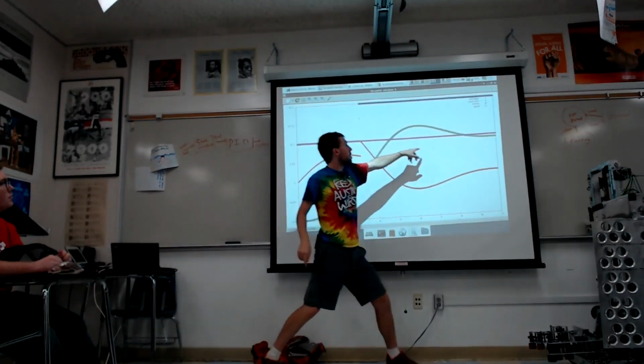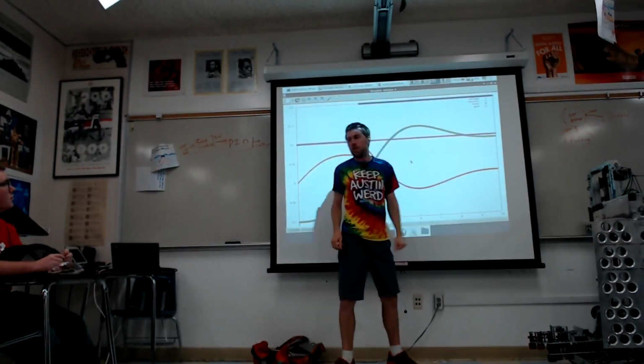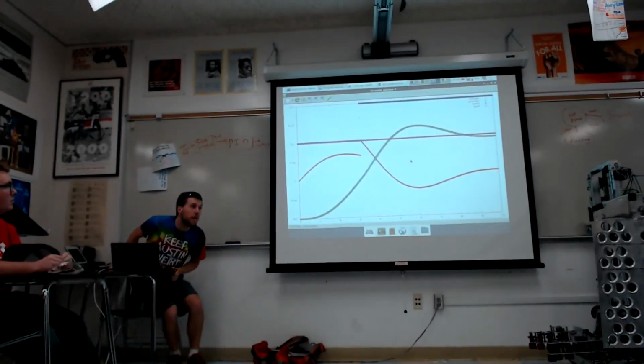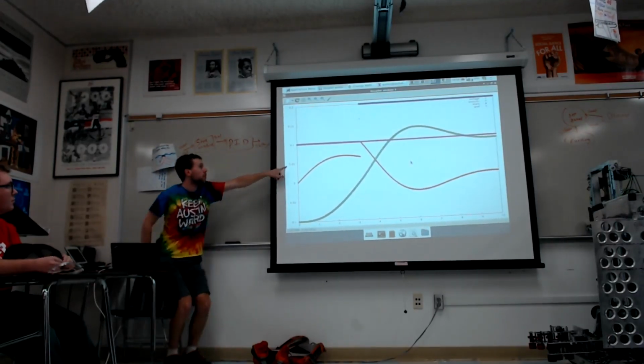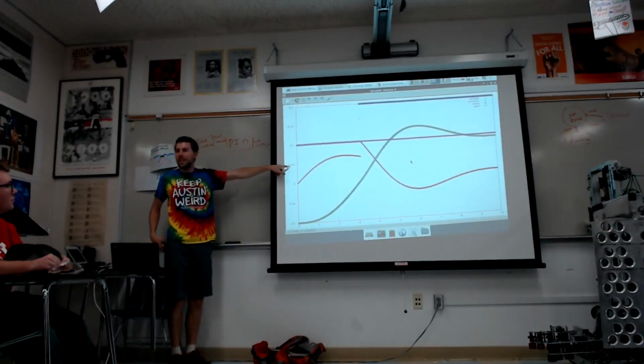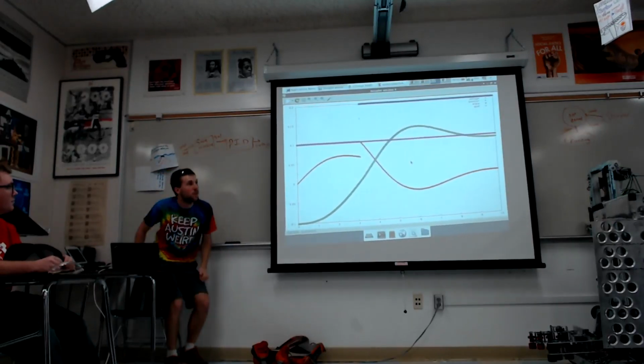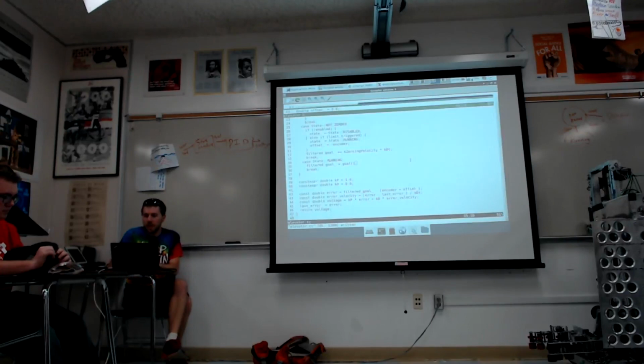Yeah, so we're starting to get there, we're just not converged. So we need to tune our control loop a little bit. I think it should be a little more aggressive. We're asking for 0.05 volts. That tends not to move things on real systems. So let's scale it by a factor of 10.